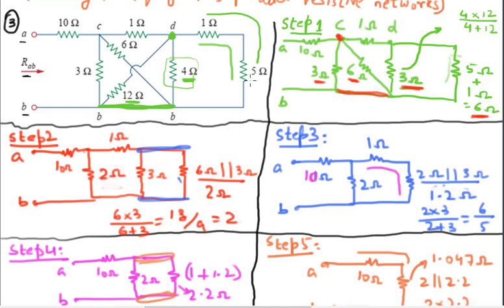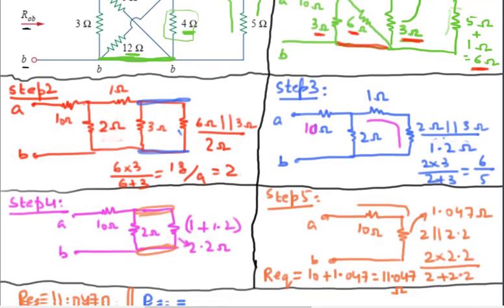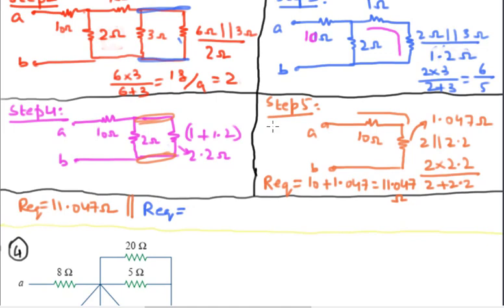So the resistance 5 plus 1 is in parallel with 4 ohms. That's the first part. So the R equivalent expression is going to look like this. I'm going to start writing from here. It's 5 plus 1 ohms in series, but their resultant is in parallel with 4 ohms.